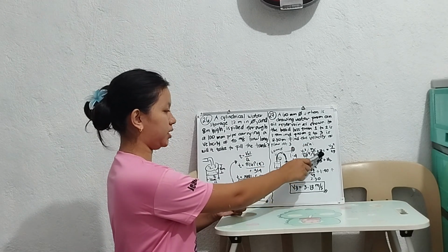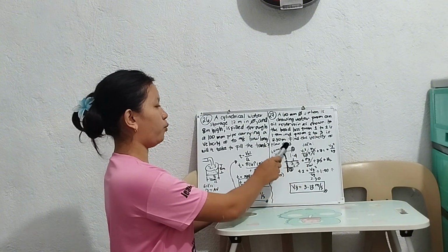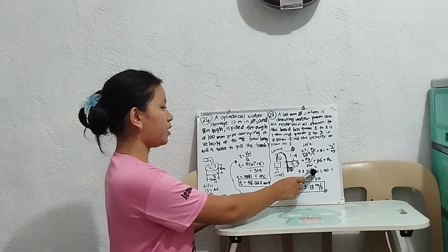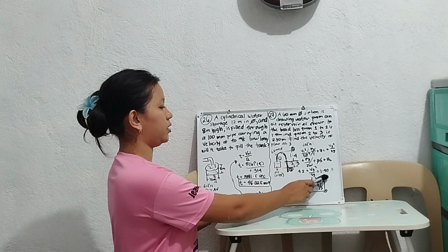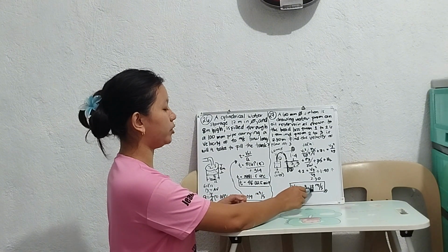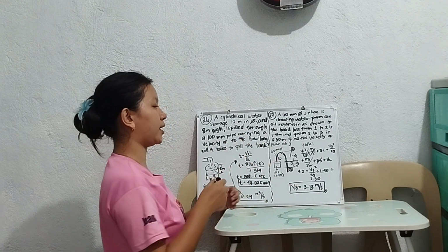And then the Z3, cross out. So we only have Z1. From 1 to 2, we have 4.2 equals V3 squared over 2G plus the 1.4 plus 2.3 head loss. So the answer will be V3 is equal to 3.13 meter per second.